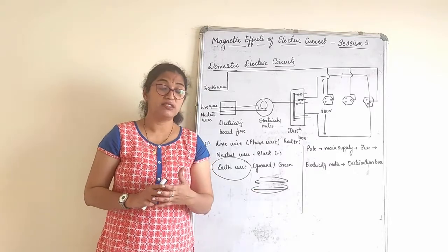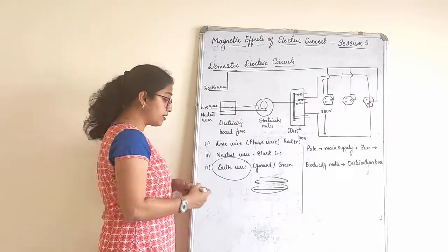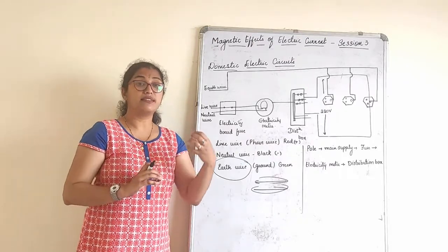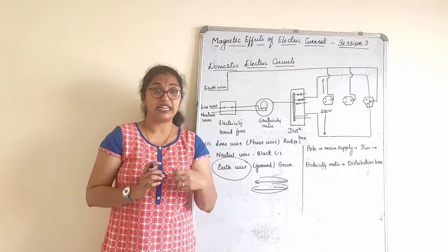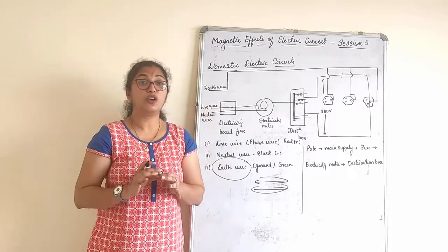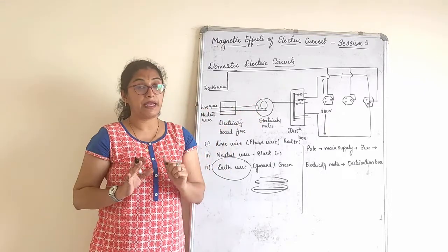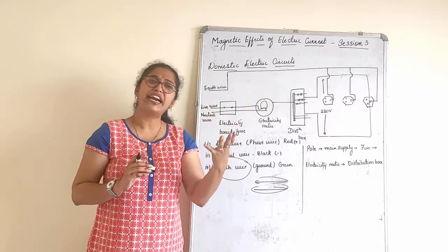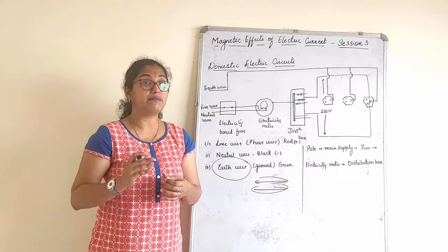There is another chance, called overloading. Overloading happens when you have a 3-pin or 4-pin socket, a multi-socket. Each socket is designed in such a way that it allows either 5 amps current or 15 amps current. In our home we basically have two types of current flow, one for lighting and another for heavy appliances. For your light, fan, basic TV and all, 5 amps current is more than sufficient. But for your heavy appliances, 15 amps current is required.